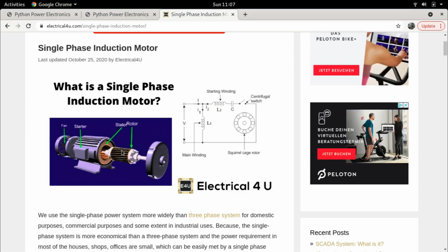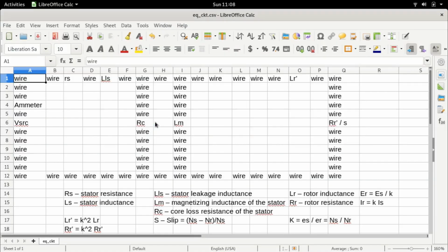This magnetic flux will result in an induced EMF, and this induced EMF will also produce a magnetic flux. Finally, these two fluxes will interact to produce a force, which will cause the machine to rotate, and the force minus the load torque will decide the acceleration of the rotor. So, on a high level, this is what we're going to do. Let's go back now to the details and try to figure this out.